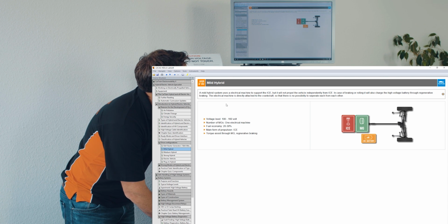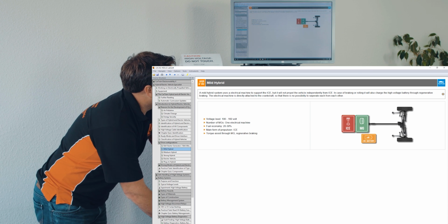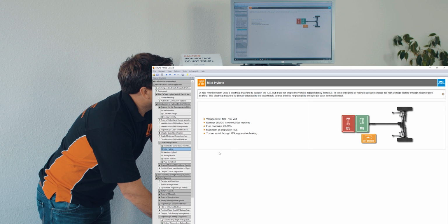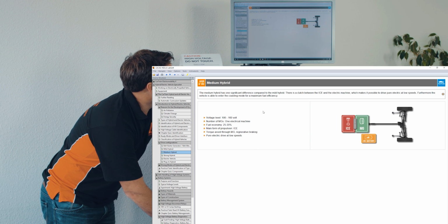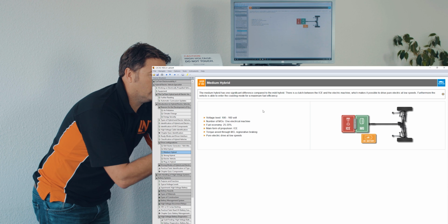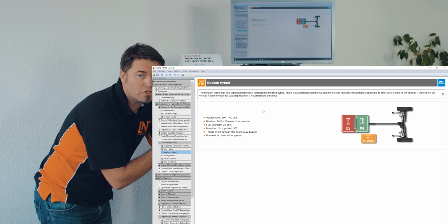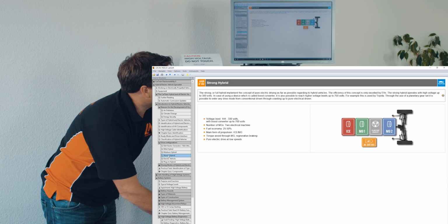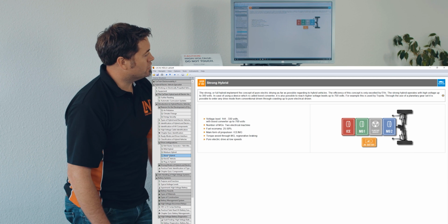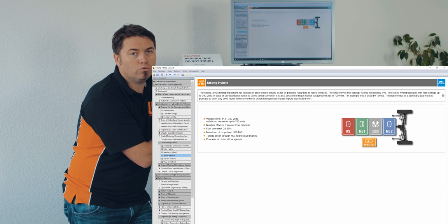So here we've got the mild hybrid, or the Type 2, and the battery will be usually a bit smaller, sometimes nickel metal hydride. Similar with the medium hybrid here is what we're calling with the clutch in between the two there. So similar to a Type 2, but with a clutch, so you can separate the two. Strong hybrid or the Type 1 Prius type, it's actually also using a relatively small battery.